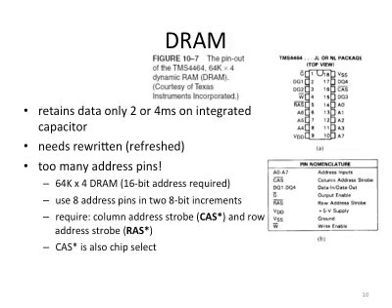When you have more bits in a chip, that means you have more memory locations. Not 1 time or 2 times more, it's many, many times more bits than an SRAM chip. So let's consider this example. Let's say we have a 64K by 4 DRAM. That is to say, for this DRAM chip, each data element is 4 bits. So the minimal unit you can access is 4 bits out of this chip, and you have 64K locations.